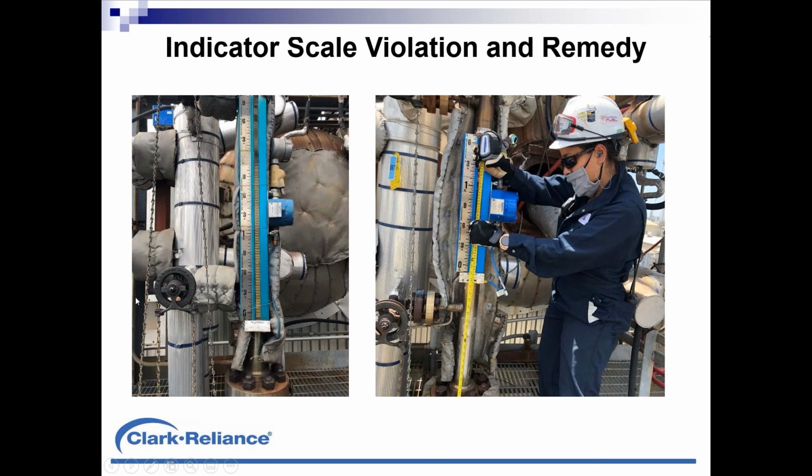Okay, here's an example of a magnetic level gauge that was installed with a scale that was too long and it was too low. And the problem with that is that lower end of that scale will never change because we'll have trapped level in that chamber. And with magnetic level gauges, you need a chamber that runs a significant distance vertically below the lower side connection in order to accommodate the length of the float. Typical floats for magnetic level gauges start at about 12 inches in length. And that's why there's a flange on the bottom so that someone can access the float for inspection.